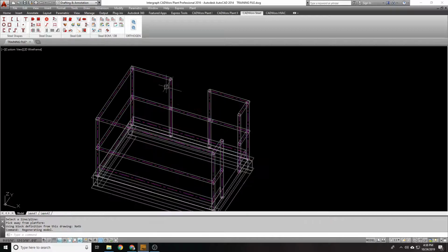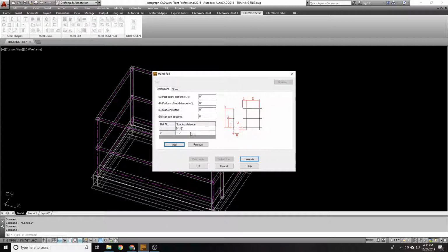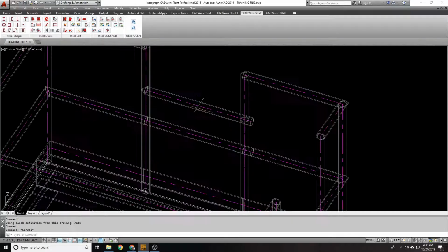But technically what I have are 3 sections. This is just a half height section, and I accomplished that by removing that top rail. You can remove and add whatever rails you want. If you want to add a rail back, you can add a rail back or add it at a custom height. Maybe we want to put a custom height for a rail, and instead of 3'7 1/4", maybe we just want to bring that section down to 2'6", and say okay. And then you have that third rail right here.